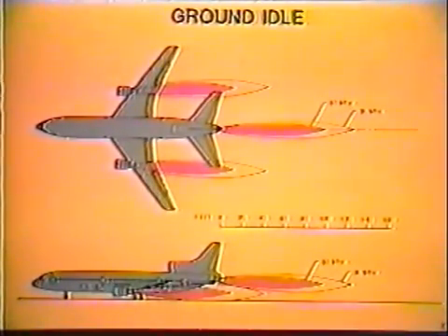Due to the high velocity of engine exhaust, consideration must be given to power application in the terminal or ramp areas. Gale force winds of 50 miles per hour exist as much as 100 feet behind an idling engine. This point for a wing-mounted engine would be approximately 20 feet aft of the aircraft tail. For this reason, it is recommended that breakaway power be derived from the wing engines.